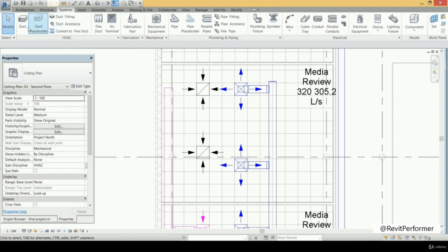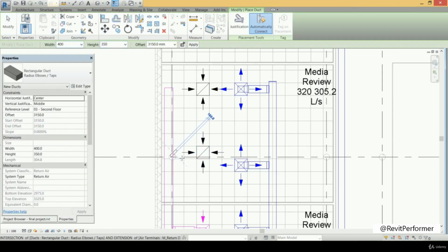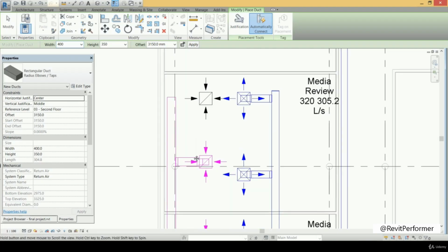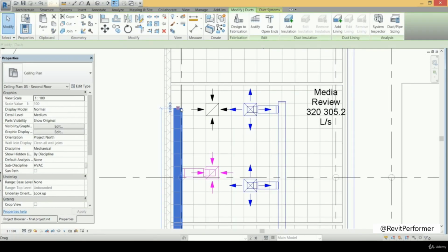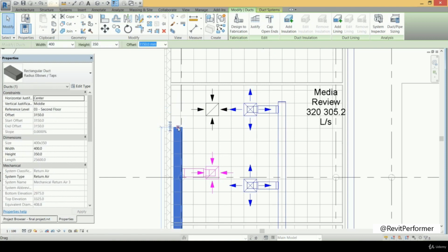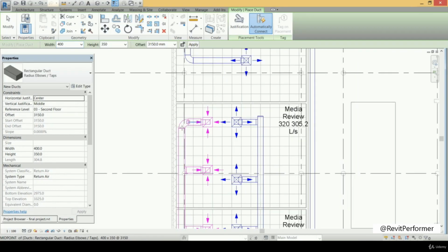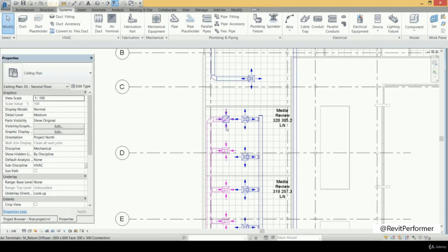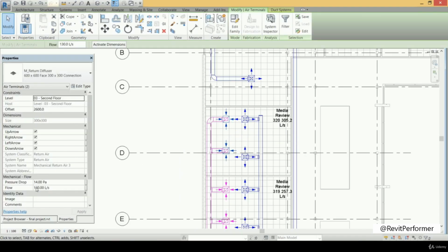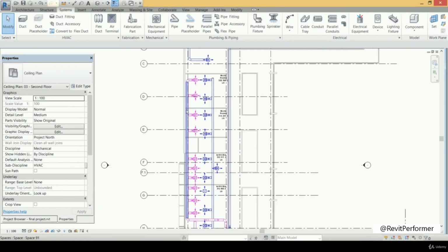So we can insert them at that point. Very good. Now we press on the duct to make the branched duct from that point to that one and another one. But at first, let's drag that duct a little bit down, and then we press a right click and draw duct, and let's move up until that point. Then we move on to that point. So it's a better design here to have that alcove. As we learned before, it makes the airflow easier, or it decreases the disturbance, instead of making the 90-degree angles here. Now we change the airflow, so I select that one and make it to be 150 instead of 130. All right, so that's about the second zone.